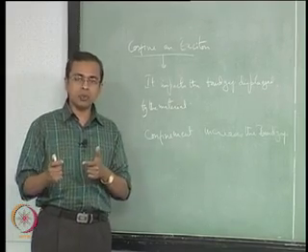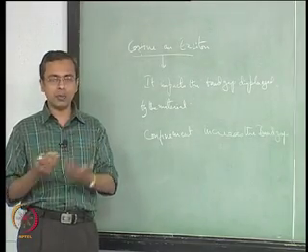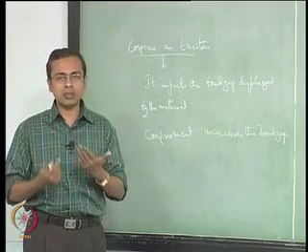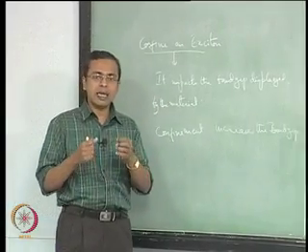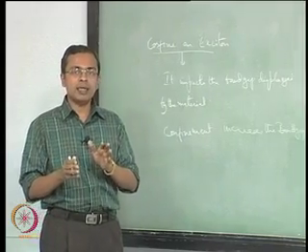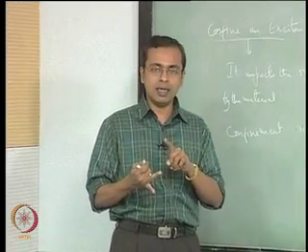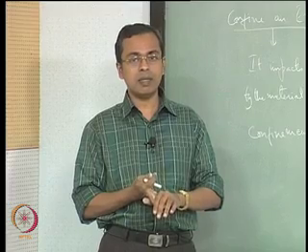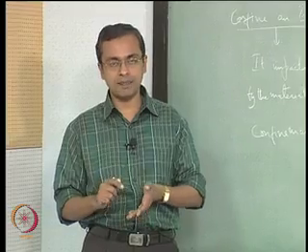Often what happens is when you do this, with heat and so on, you can have some material diffusing into each other, and as a result over a period of time dissimilar material contact is usually a bad idea to have in most engineering senses. In many places in engineering we find that when we have dissimilar material contact there are a lot of problems associated with them in terms of sealing, in terms of any diffusion that might occur between them, any corrosion that might occur as a result of that contact, and so on.